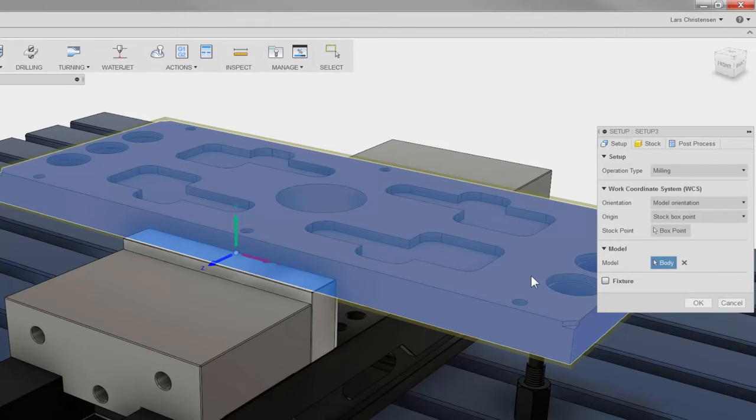Next, I will concentrate on the XYZ axis and the work coordinate system. The work coordinate system is also by many referred to as G54, G55, and is where your part 0 is located. Out on the machine, your XYZ axes are pretty defined, but on a CAD model there's no set rule. Many times when you receive a model, an axis will be flipped in the wrong direction.